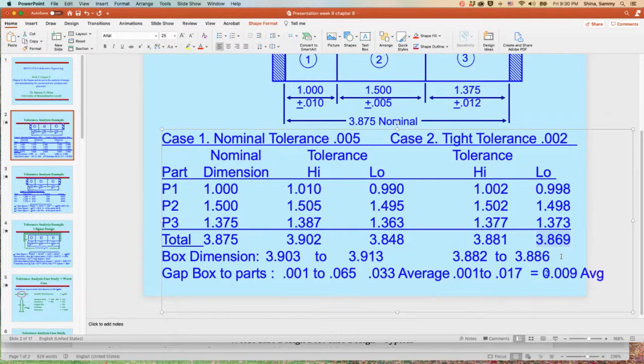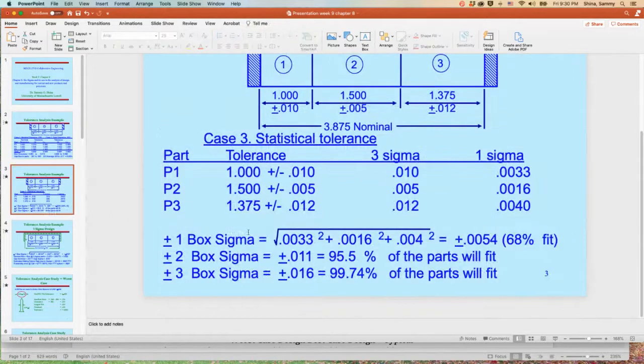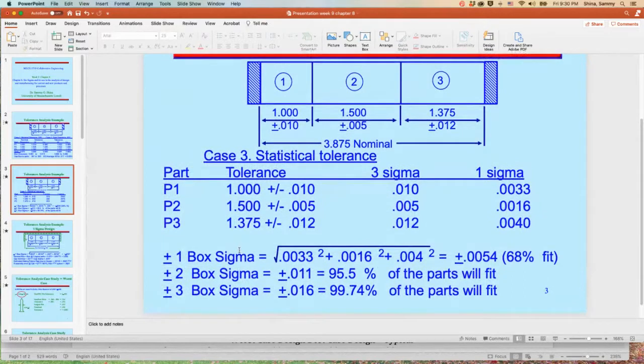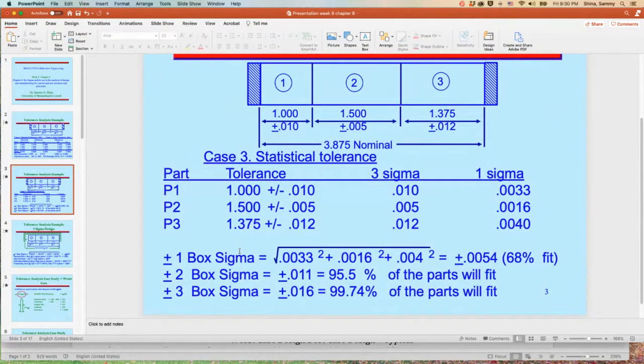So is there another way of thinking about this? Okay, so one way of thinking about it is, well, let's say use the normal curve as opposed to a worst case analysis. We can tolerate some failures. So in this particular case, we're looking at the same design, only this time we're going to present it in a tolerance analysis way. So what we say then is that each plus or minus represents 3 sigma.